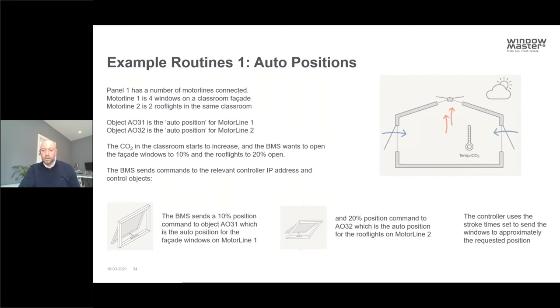And the motor-link controller then knows they're 24-volt DC actuators, it knows what the stroke time is, and the controller then powers those actuators for the correct amount of time to send the windows to approximately the requested position. Really nice and simple.